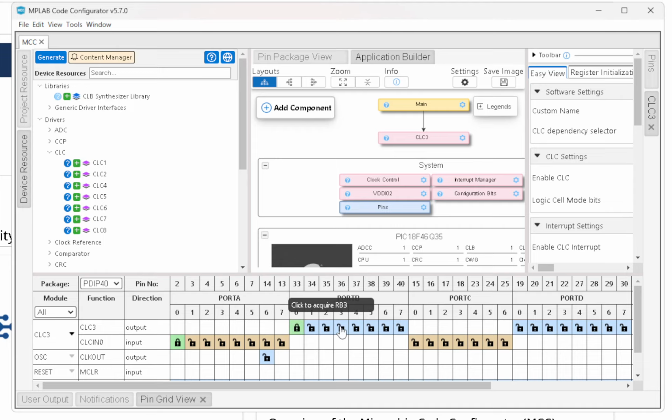My LED output is going to be on those two. There you go. And my input, CLC, is going to be A4. That's where my switch is. And that's in the layout in the code that we'll see. So I am going to push a button on A4 and two LEDs will come on over there. But how? That's the question.